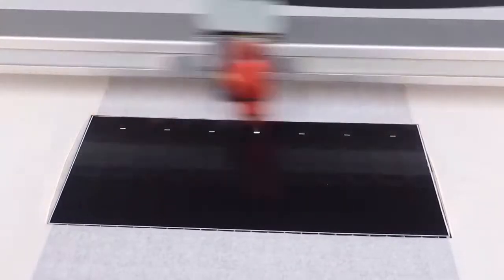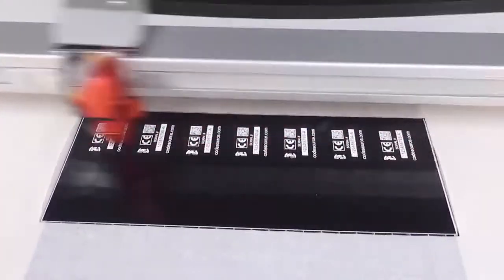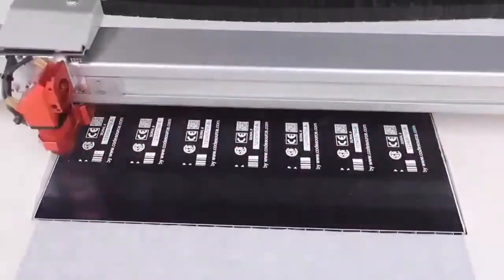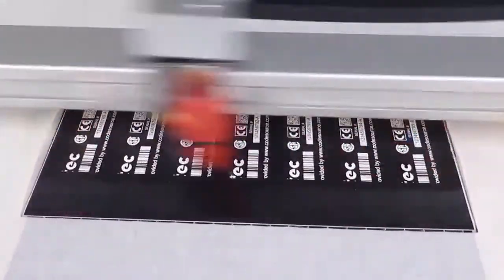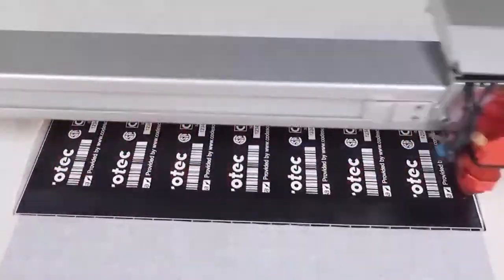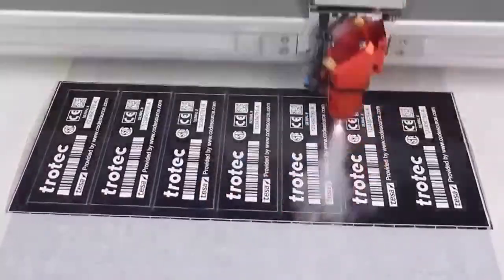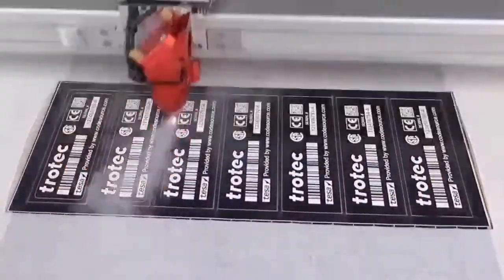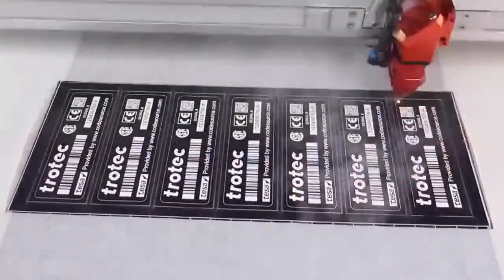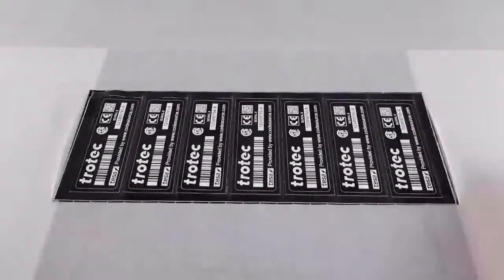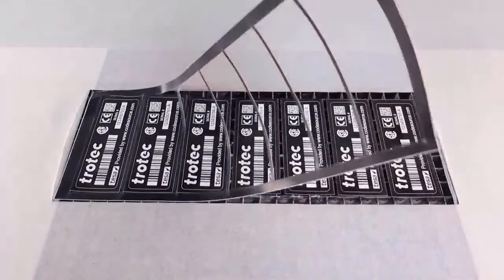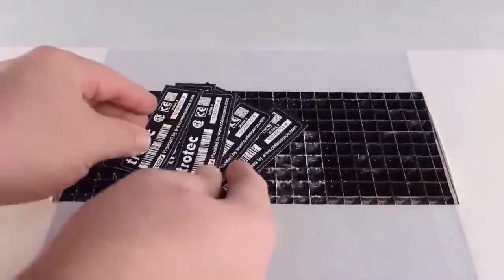So this is the material actually running. You can see this is a sheet. I've taken an entire sheet here, and then we'll engrave the entire graphic, multiple graphics, of course, with a different serial number on each one. You can do that. That's the other nice thing about the Galvo fibers, the serialization is built in, so you can have it automatically plunk out different serial numbers per label. And it can also change the QR code or the barcode or UID code or the linear barcode all at once. But as you can see, nice, clean, high contrast mark.